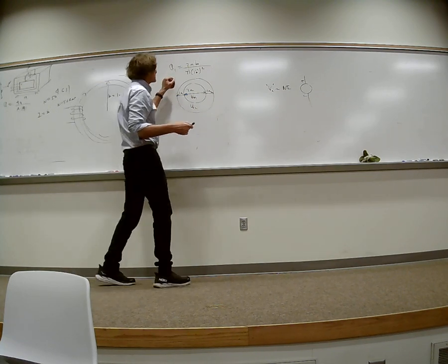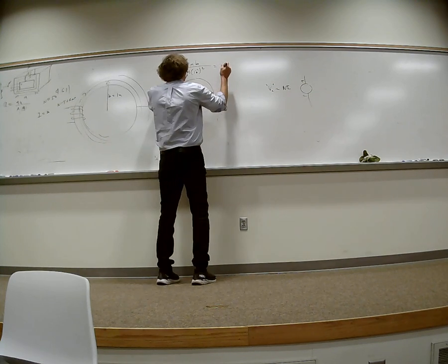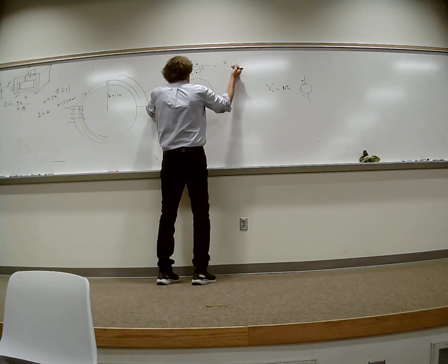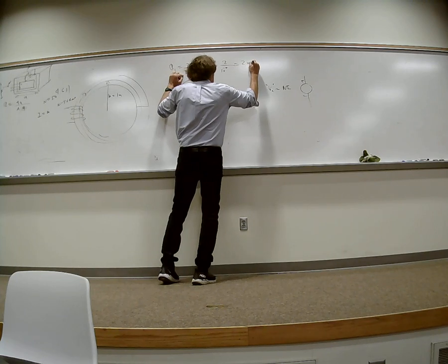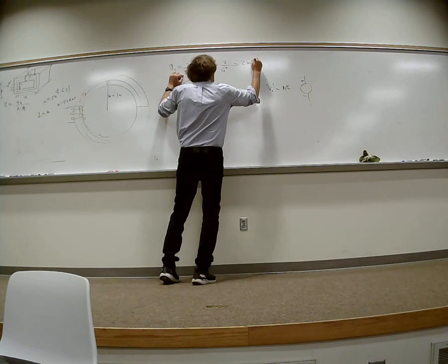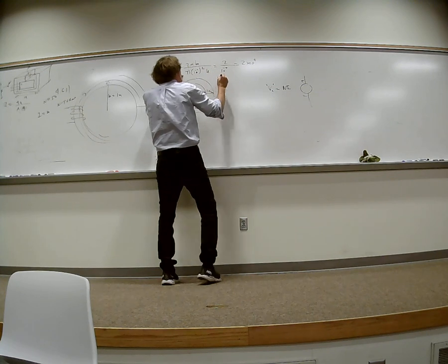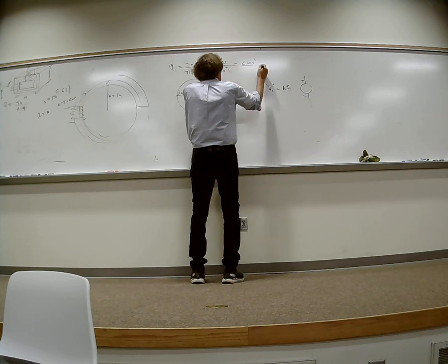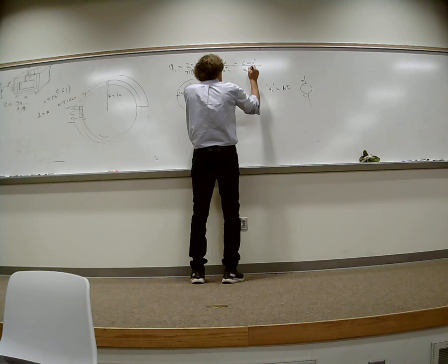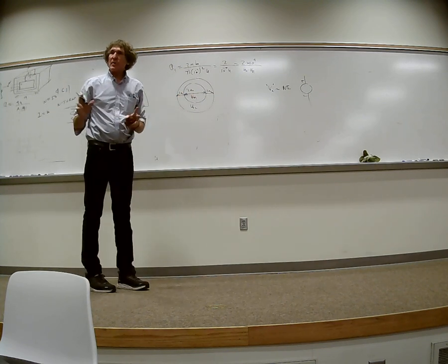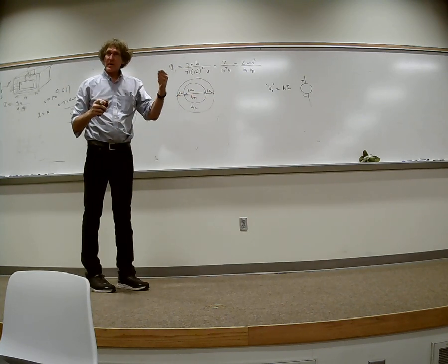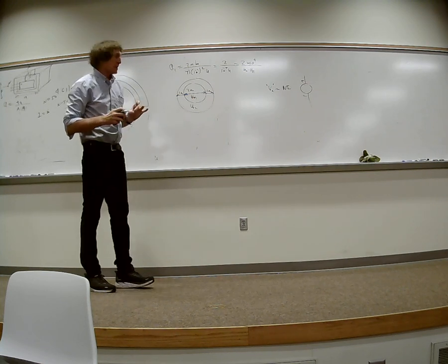So when I look at the reluctance R1, the pi's cancel, I have 2b, b is 1, over 10 to the minus 2 squared, or 10 to the minus 4. So it's really 2 times 10 to the 4th, and I forgot to divide by mu, which is mu 0 times mu relative 1. Can everybody follow me on that? Don't worry about mu relative 1 yet. Just follow me as far as the method. I'm getting the reluctance of the inner one.